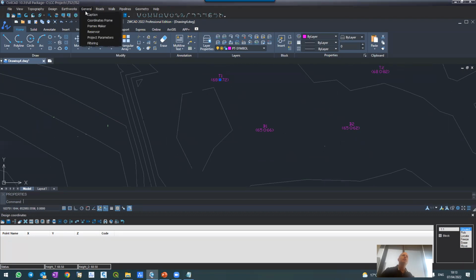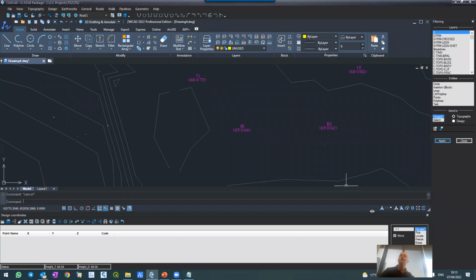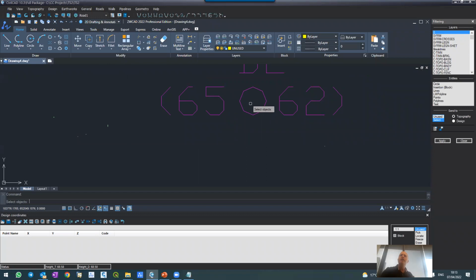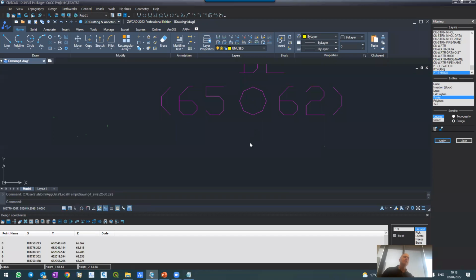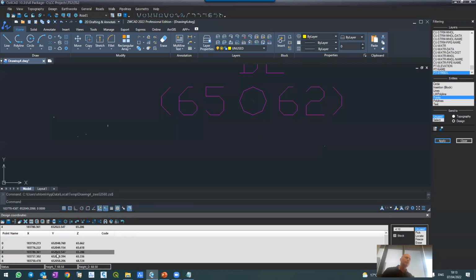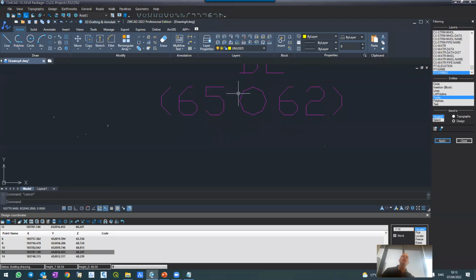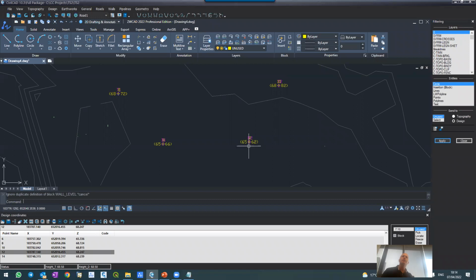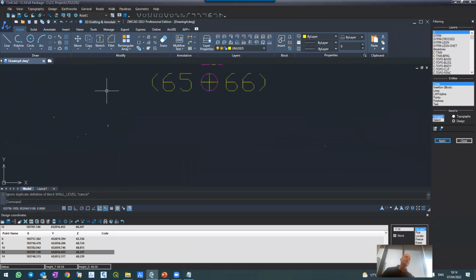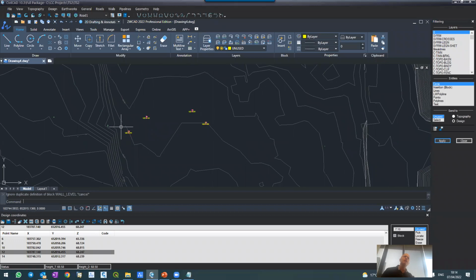I'm going to general, filtering, and tell the software to select which layer, like I did with the break lines. I'm selecting this layer. It says it's a point in PT symbol, okay? Yes, okay. You see what happened? All the coordinates appear here. It went through the layer and created a file with points. So if I refresh now, I'm supposed to see it as a new layer on top. Yeah, you see? Exactly. It gives a different name, but it's not so important for me. The important thing is that I have the points now.